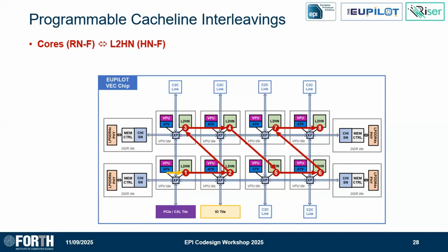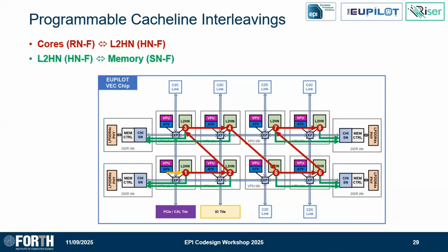Here, we change the order. It's a modified Morton order, a Z order. So it goes like this. If you start fetching, it will localize the traffic first here, then move the localized traffic here, and keep going around. This is part of the interleaving. Of course, it can be programmed, but this is one of the things that we hope can help lots of applications.